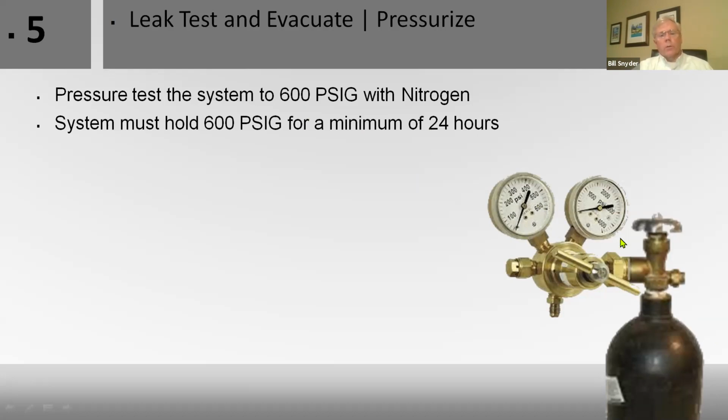You say, why 600 pounds? Our relief pressure valves on our units are just about 700 pounds. So you're not going to blow any relief or anything. 600 pounds is good. If it doesn't leak at 600 pounds, it won't leak under normal applications.